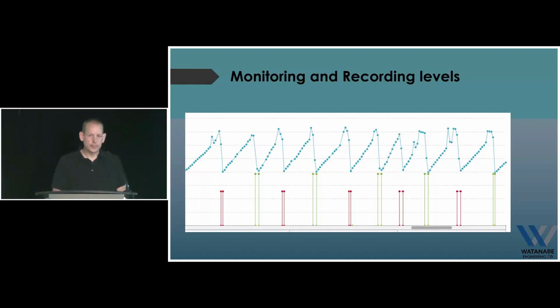We're capturing all that data, keeping it all, and I can keep an eye on the reservoir, or if it was a sewer station, remotely. If they were having issues, they just call me up, I take a look at the trends and see what's going on. So think about remote stuff. If you haven't got SCADA, I seriously recommend you start thinking down that route. Data's worth a lot of money.